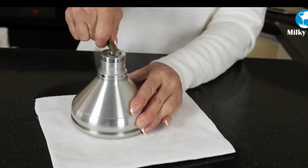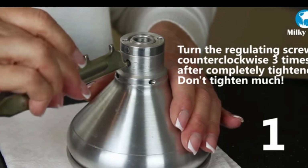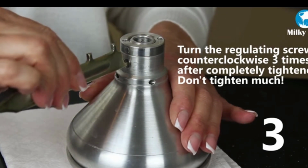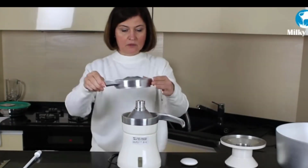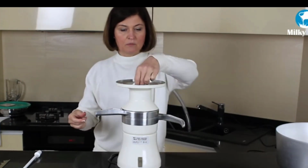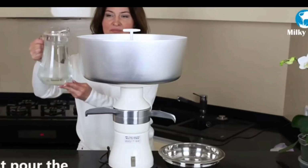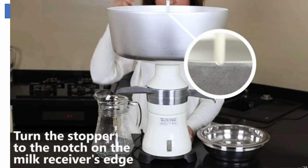Now generally the milk is preheated at 37 to 50 degrees before separation for optimum results. This makes the process easier and more efficient as warm milk is less viscous than cold milk. Milk is fed down an inlet tube into the separator bowl where it rotates and moves up through a series of aligned holes in the disc rack. Then the inflow of milk is regulated by adjusting the milk inlet valve to the separator.